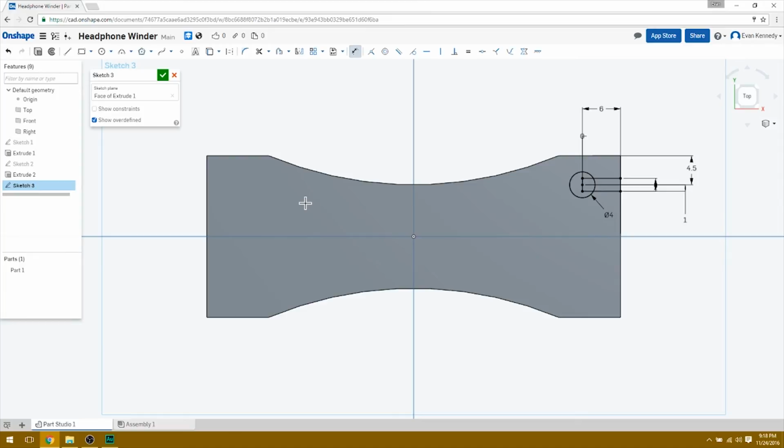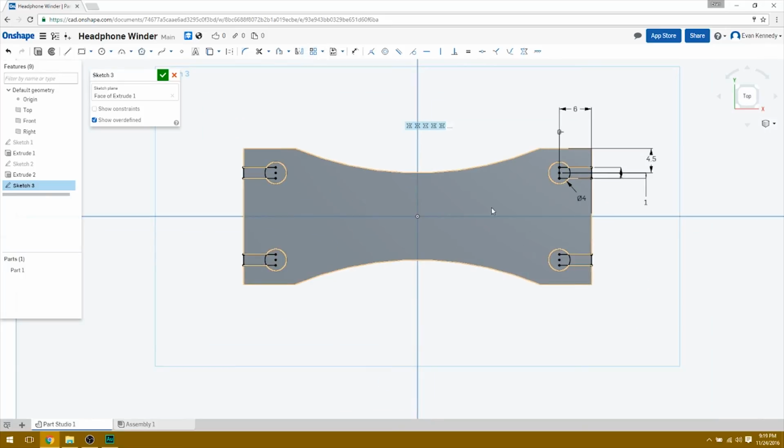So what I actually usually do here is I use 2 separate mirrors. I'm going to do it once, mirror it across this line, and I'm going to choose my circle and these 3 edges of my rectangle, and then I'm going to deselect my mirror tool to apply it, and now I'm going to do another mirror across this line, and I'm going to select all of them. You can see it's applied that twice. So there we go, there's my sketch ready to be extruded.